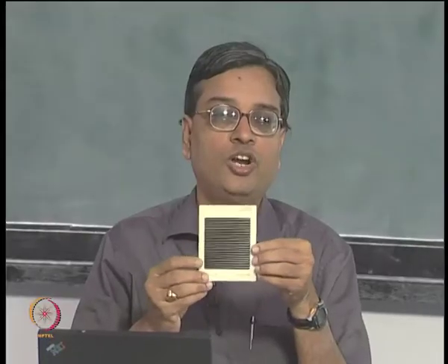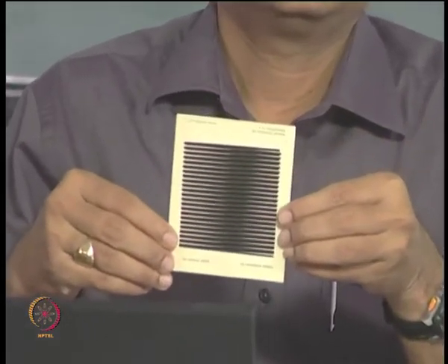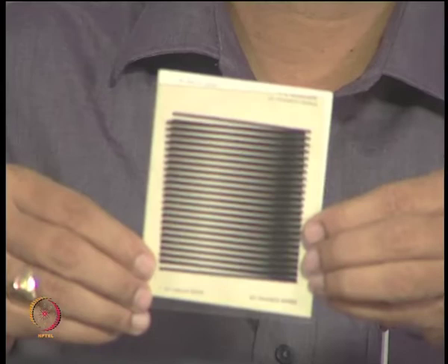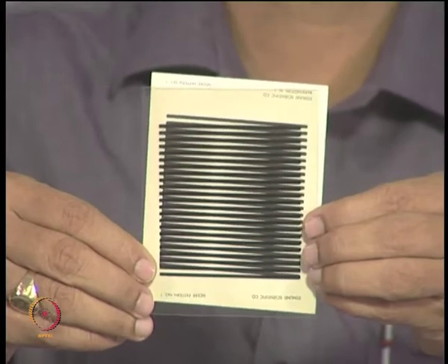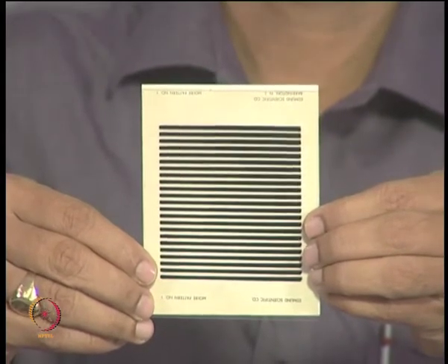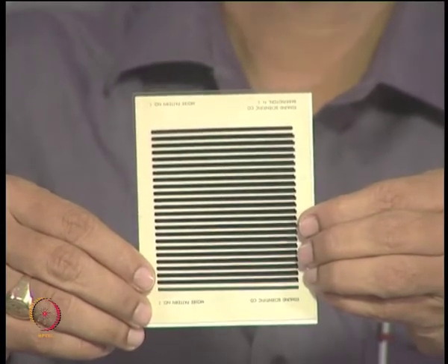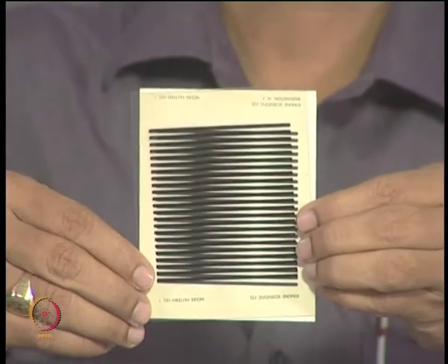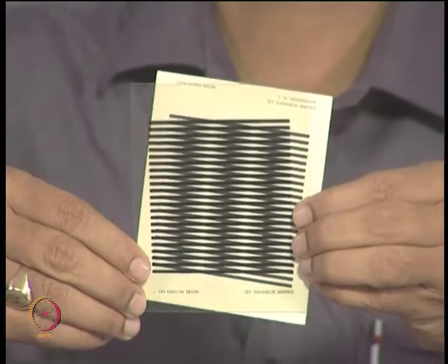And in Moire what we also saw was, I have a grating which I had shown, and what you will have to notice is, when I have this grating, I make a rigid body translation and rigid body rotation. I see fringes, we get excited to see fringes, but you should implicitly understand this is a nuisance in Moire, because in Moire I would like to find out what is the effect of stresses or strains introduced in the material, not rigid body rotation and rigid body translation.